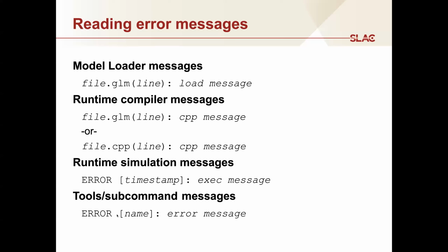It is fairly usual, it's not universally true, but it's quite common, that if you have the debug flag set on, the error from a tool like Python will be followed by a traceback, which for those of you who work with Python is really useful for identifying the source of the error. And what it means is that if you're having troubles identifying the source, if you turn on the debug option and run it again, you should be able to identify where the error came from. So that's generally how you read outputs from loading and running simulations.